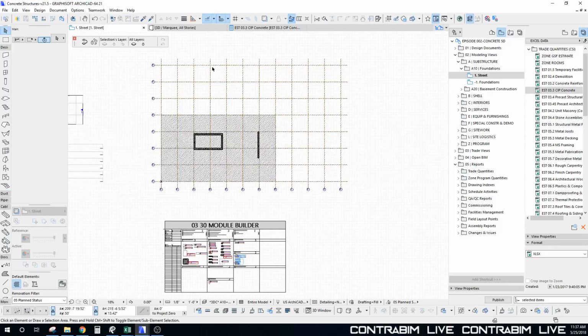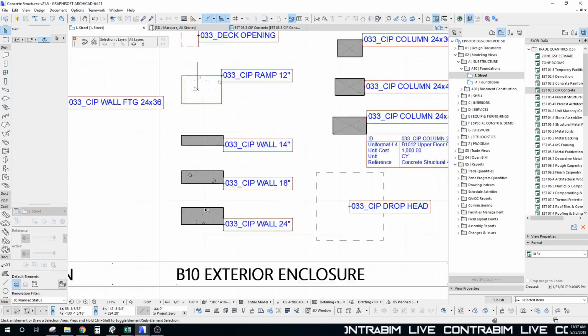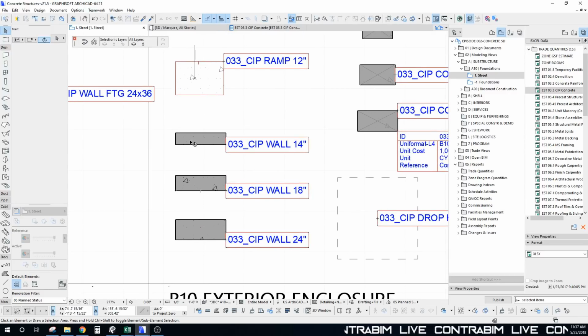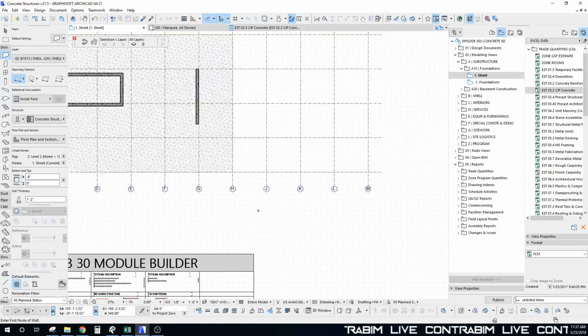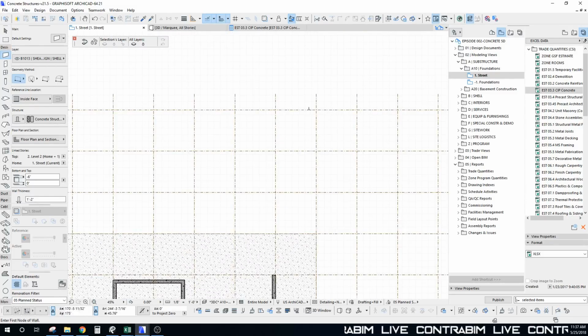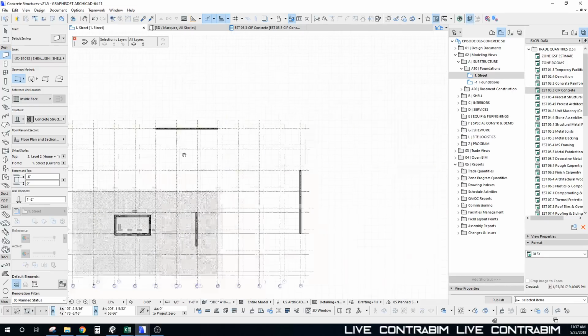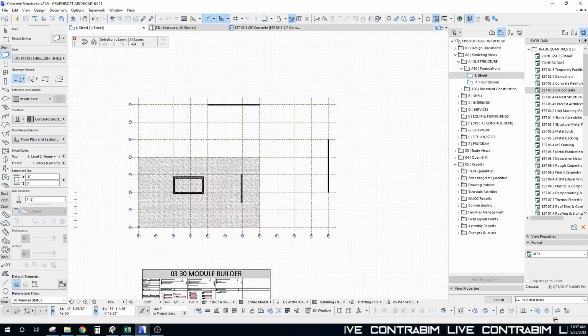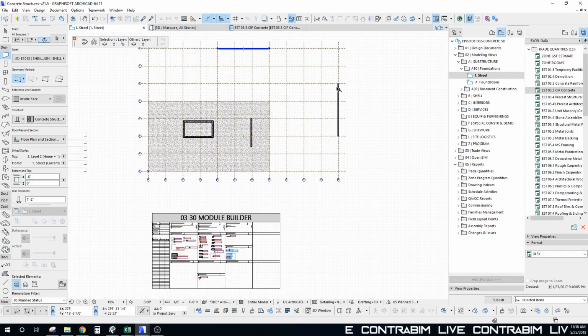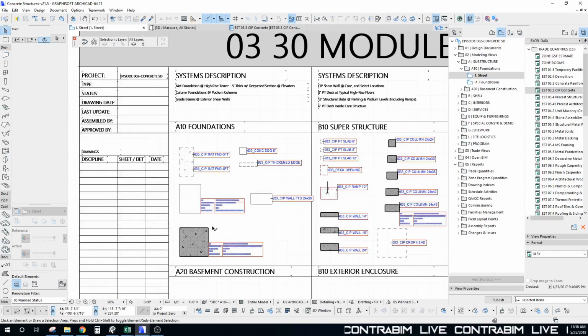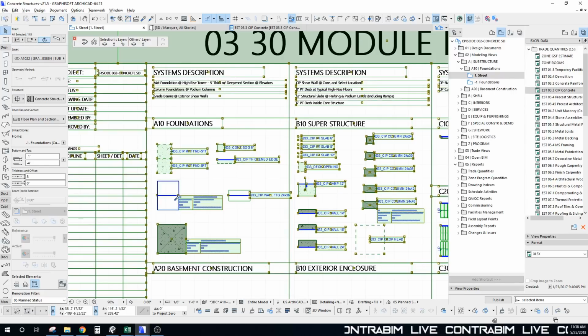Okay, so let's take that shear wall and add in a few external shear walls around the perimeter of the building here. Let's grab a smaller one because this is only going to go up so far. Let's snap that over 75 feet. That's fine, 75 feet in that direction. Just set the bottom elevation to make that our -1 where we're starting.